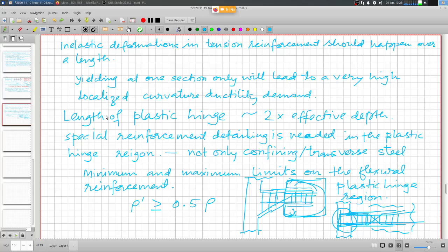So the actual strength provided in the section is more than what is aimed at the target strength, and the column capacities have to be more than the estimated actual capacities, accounting for the overstrength. That is how it will be possible to avoid development of plastic hinges in the columns, and limit the development of plastic hinges in the beams.